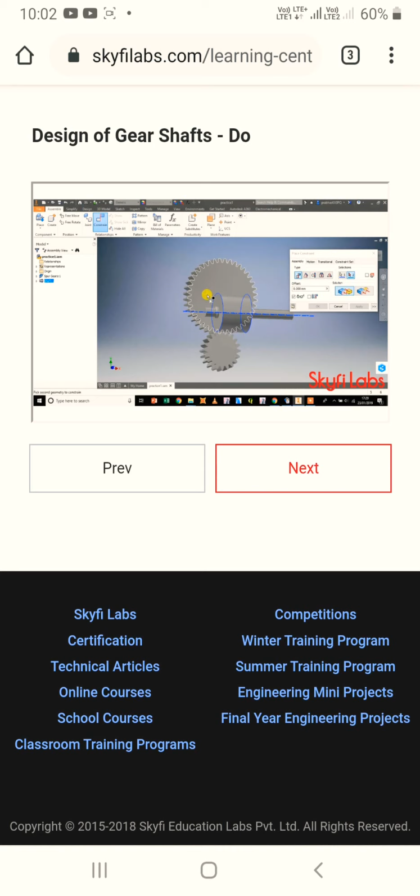Once that is done, we can see that the selection 2 in the constraint menu is highlighted, prompting us to make the second selection. In our case, the second feature is the axis of the spur gear. To avoid any mistake, we will select the axis of the spur gear from the model tree instead of the gear assembly itself. This is a good practice to follow, especially when we have multiple parts in our assembly.